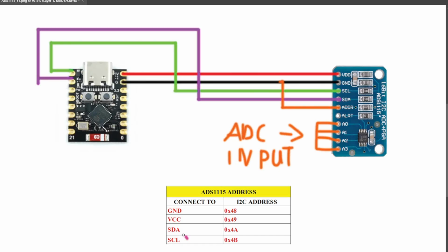During my testing, I discovered an issue when connecting the ADDR pin to SCL to select the I2C address.